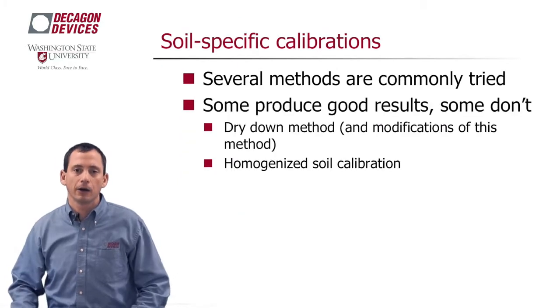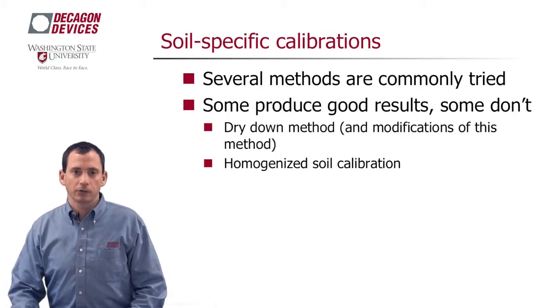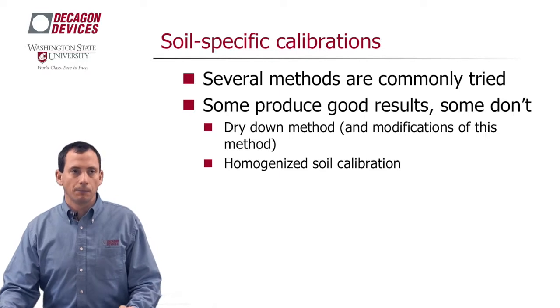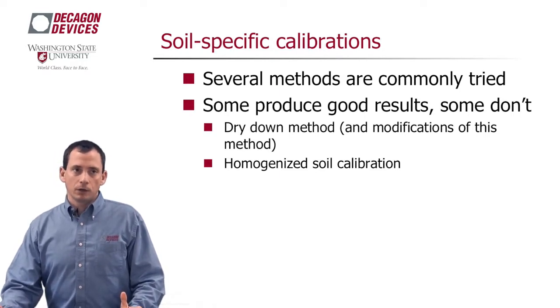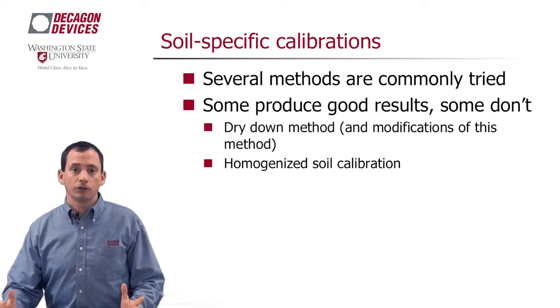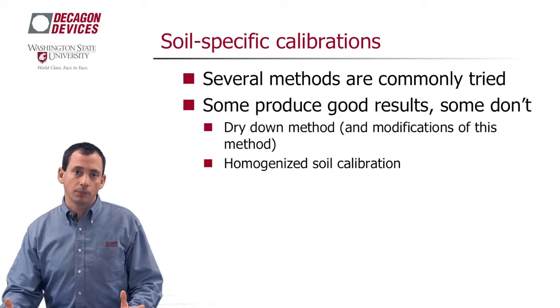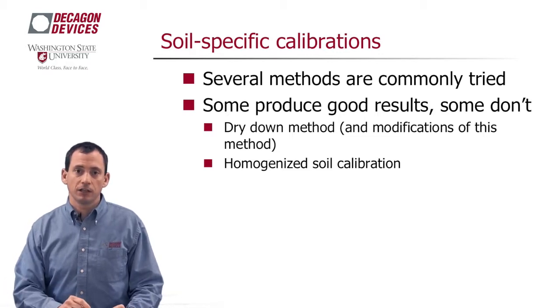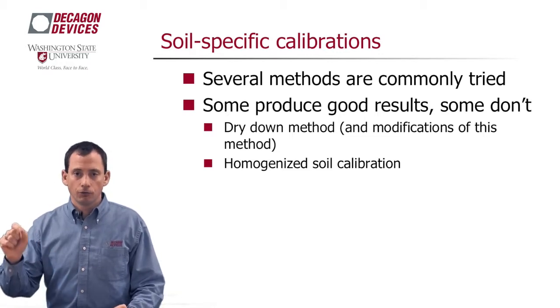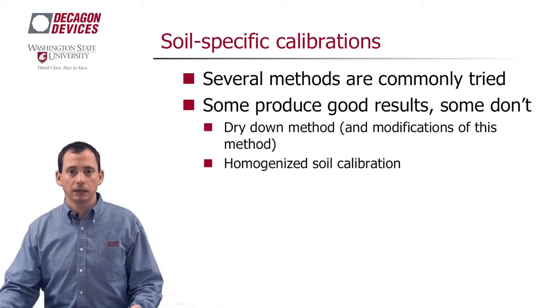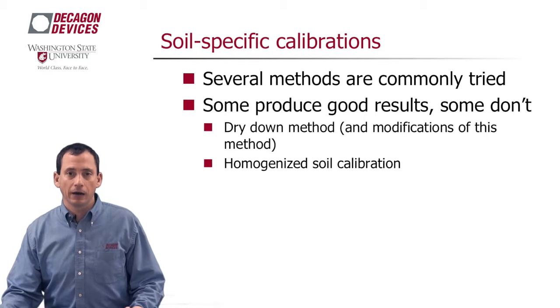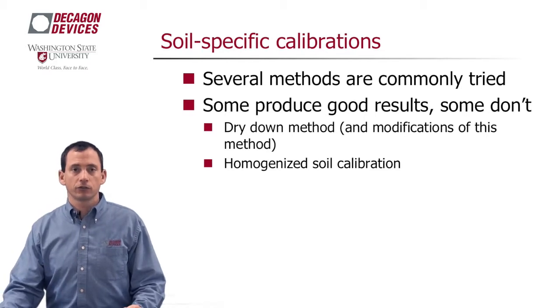So let's now talk about, I've alluded to it a couple of times, I get ahead of myself, sorry, but let's talk about soil-specific calibrations. What do I mean when I'm talking about a soil-specific calibration? What I'm talking about is determining the relationship between dielectric permittivity and water content for your particular soil. And this is really a key for getting the best accuracy out of your dielectric sensors.